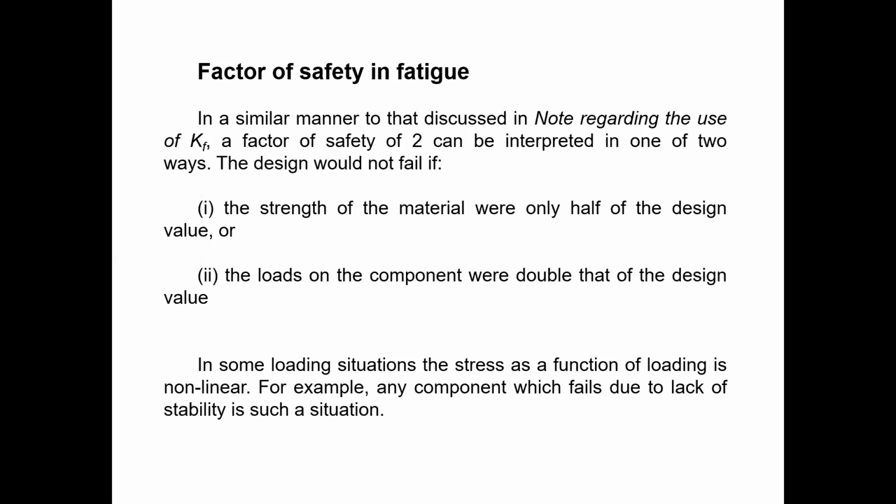So it can be linear or non-linear. If it is linear only, you can use stress and load both. If you use the FN curve or if you use the SN curve, it doesn't matter. But if it is non-linear, you are in trouble. Okay, so that non-linearity between the load value and stress value will happen because of the element stability.